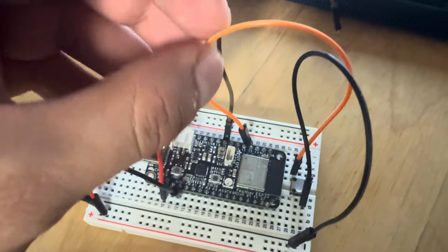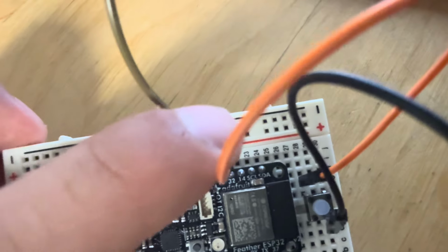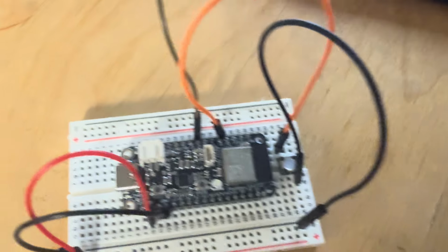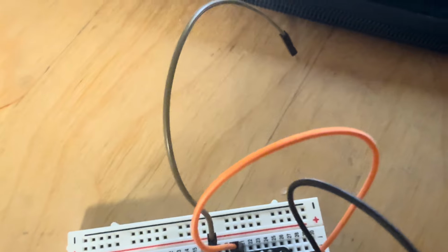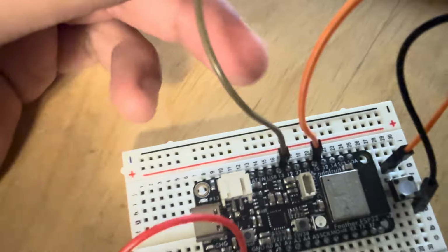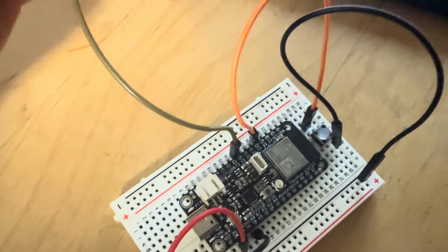And then on the other side of the push button, I connected it to GPIO 32, so it can do the wake up for the EXT0. And then also I have a touch pin. So basically when I touch this little thing, it will turn on the NeoPixel. And that's pretty much it. And that pin right there will be just pin 12.